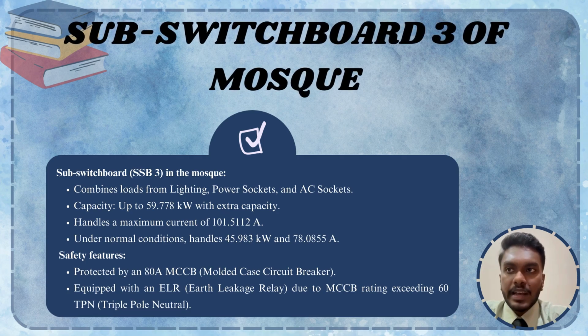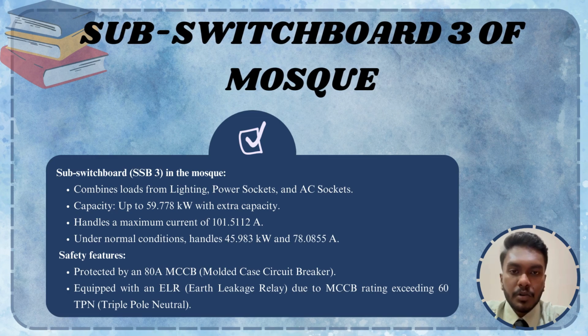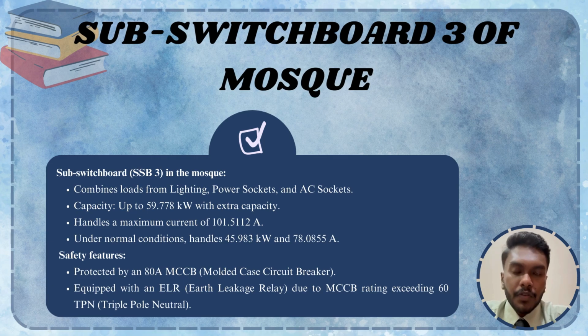The sub-switch board SSB3 in the MOSC combines the load from all three main distribution boards: lighting, power socket and aircon socket. It can handle up to 59.778 kW with extra capacity, drawing a maximum current of 101.5112 ampere. Under normal condition, it handles 49.983 kW and 78.0855 ampere. For safety, it is protected by an 80 ampere MCCB and ELR earth leakage relay.